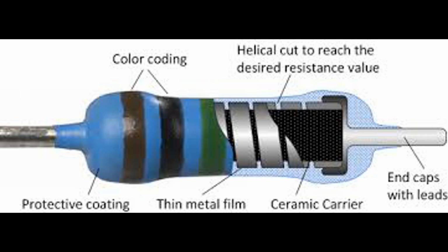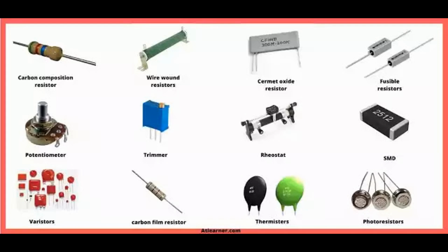at higher frequencies. 4. Inductive and capacitive components. Inductors: heat is generated due to the resistance of the winding, copper losses, and core losses, hysteresis, and eddy currents. Capacitors: while ideal capacitors do not dissipate power, real capacitors have equivalent series resistance, ESR, leading to heat generation during charge and discharge cycles. 5.